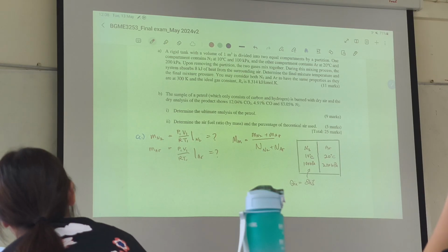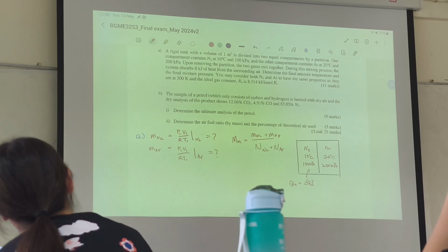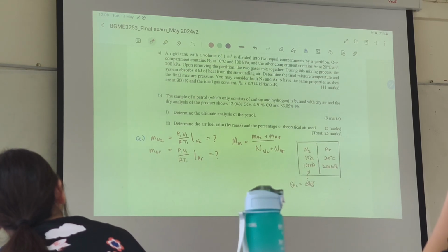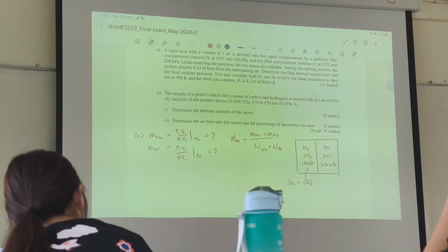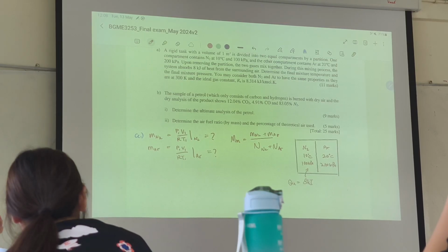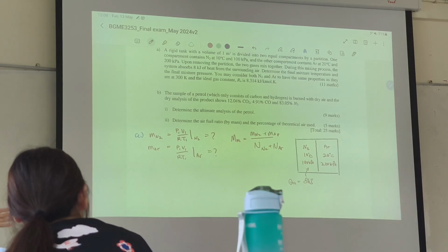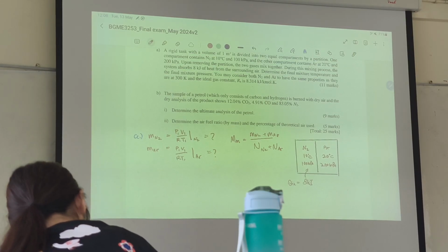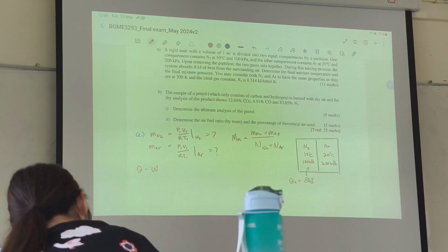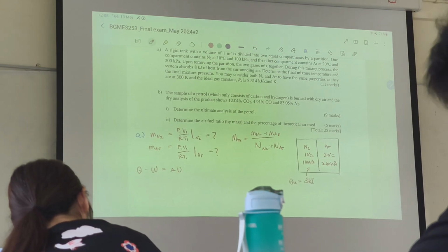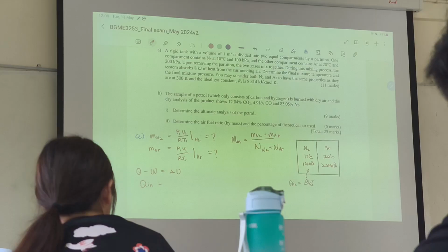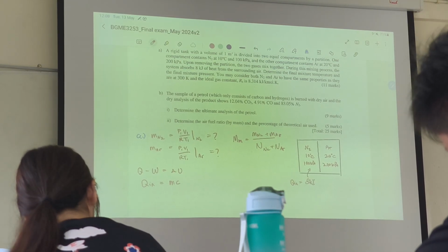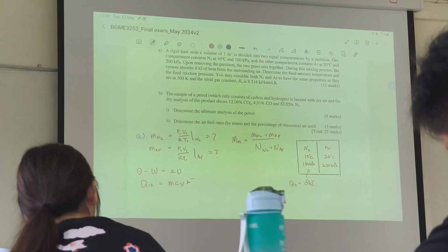Right, so actually you can use heat capacity. Okay. You will need to remember that we are still doing thermo here, right? So what system is this? This is a closed system. Even if you remove a partition, it's still a closed system because everything happens inside. So meaning this whole thing, the energy transfer here equals delta U. So what we have here is QE. There is no work. And here will be MCV delta T.